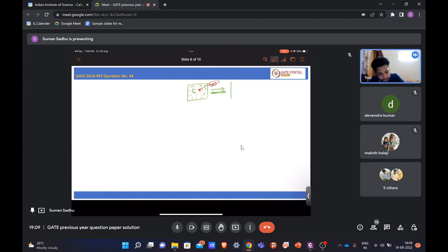That is the short range ordering, but that regular pattern is not stable when you are at Tm or at a temperature greater than Tm. So what will happen? Suddenly this kind of regular arrangement will form and suddenly it will break apart. That regular cluster is forming and it is breaking again. So those kinds of clusters are not stable at the melting temperature or higher than the melting temperature.